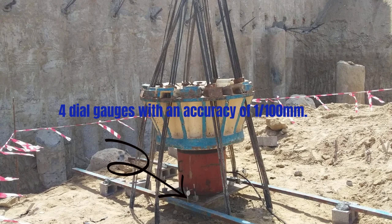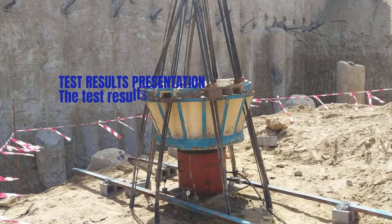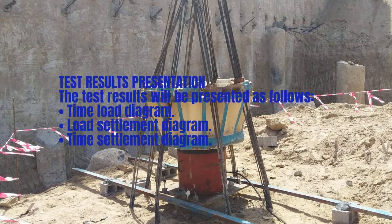External leveling, measurement of pile movement: the settlements are recorded with 4 dial gauges with an accuracy of 0.01 mm. Test results presentation: the test results will be presented as follows: time-load diagram, load-settlement diagram, and time-settlement diagram.